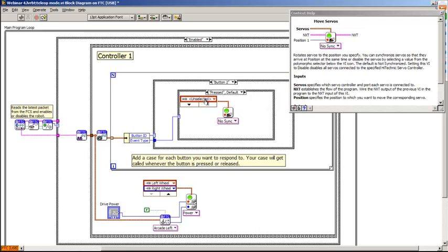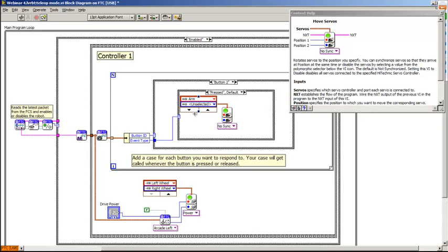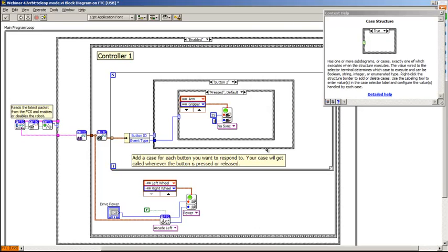I'm going to pick my two servos, which of course are arm, and then I'm going to click the triangle to expand a second one to choose gripper. Now that we've got arm and gripper, two choices selected, we automatically get two input terminals for our positions. I'm going to right click to create a constant on my arm position of 25, and on my gripper position create a constant of 200. What that's going to do is when my teleop code runs, if I ever press button 2, it's going to put our arm and gripper servos to a known position of 25 and 200 respectively.